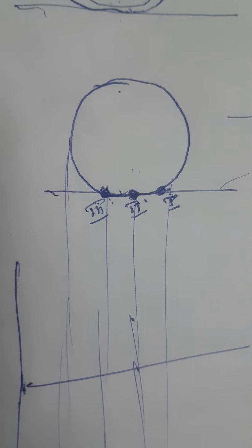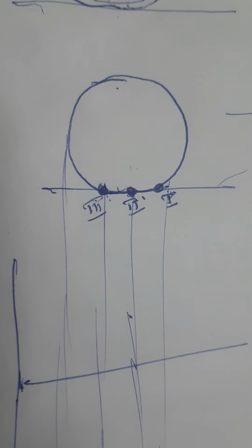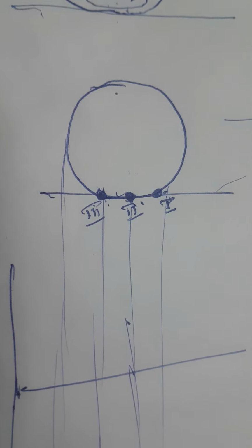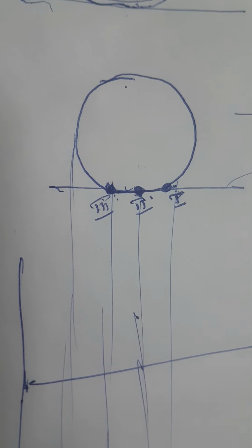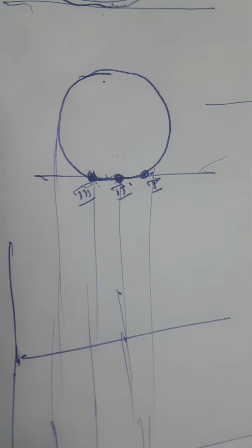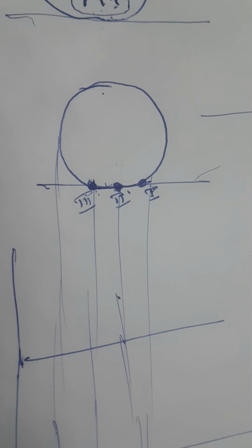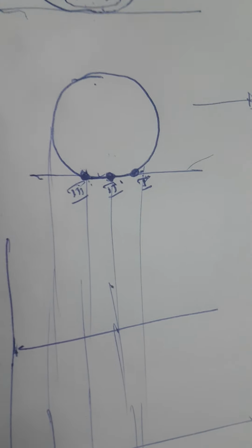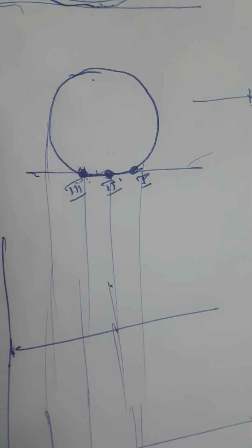So the reaction force given by the ground surface must be slanting. So the tire pressure will vary. This unsymmetric distribution is because of the viscoelastic nature of the tire material.